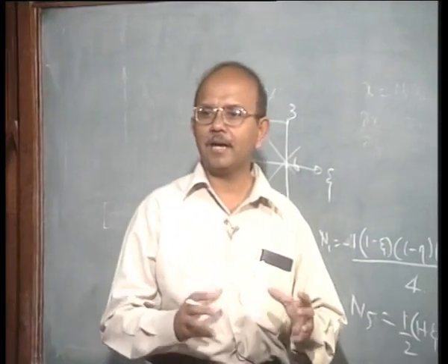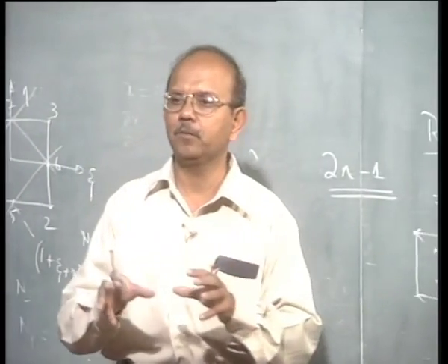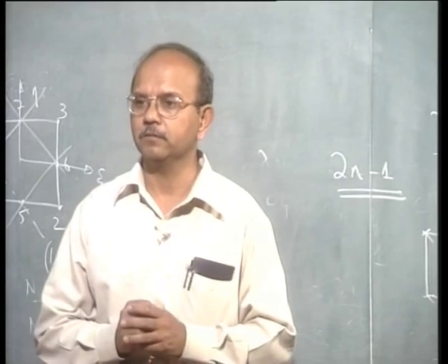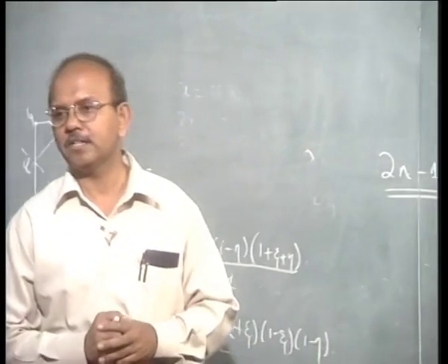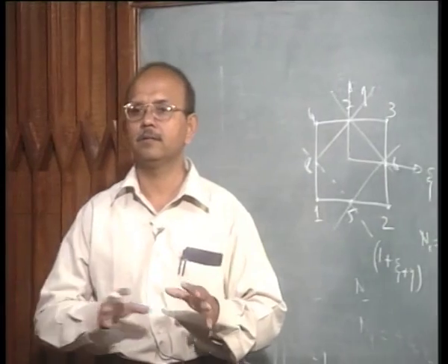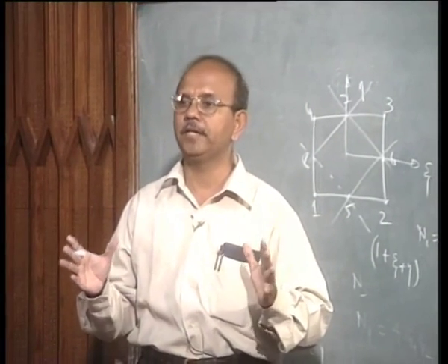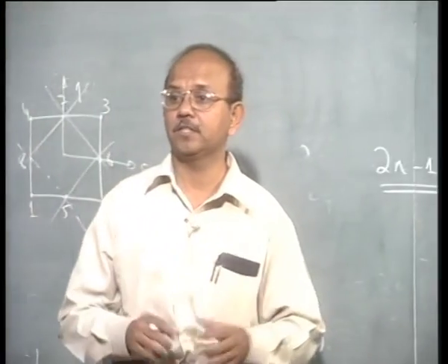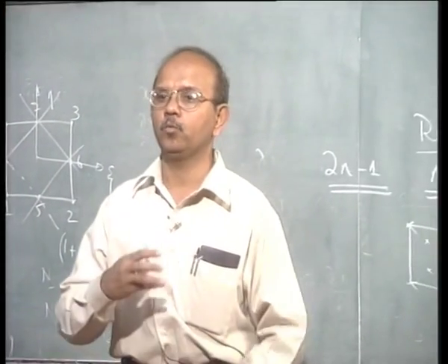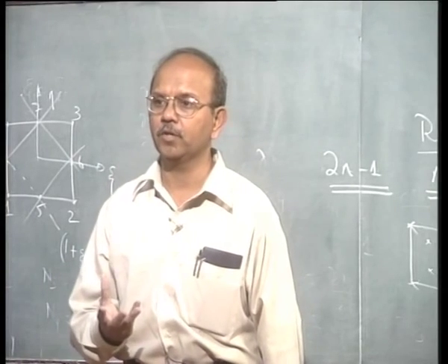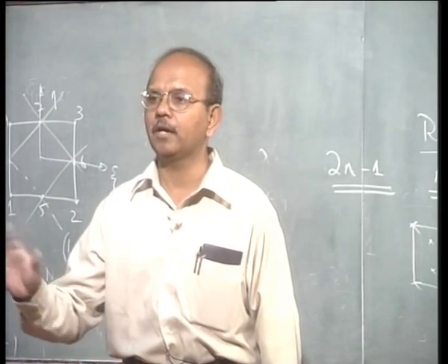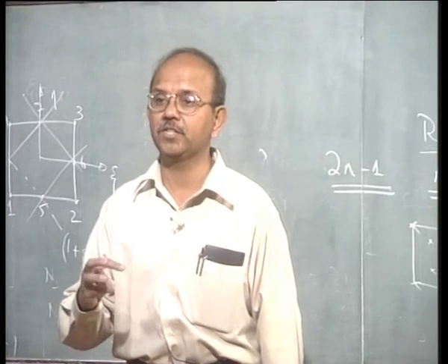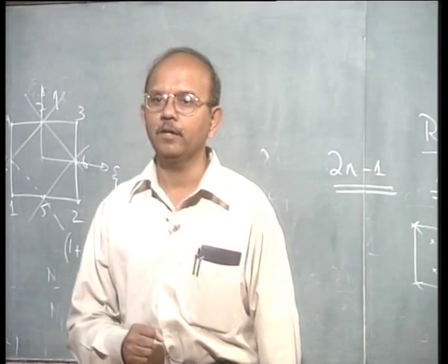Now for that we have to understand finite element, whatever I have done so far, in a proper perspective. After all, in finite element, what is that we did? We broke down an infinite degrees of freedom into a finite set of degrees of freedom. So in that process, what did we do? We stiffened the structure. We said that look, you can't have all your infinite degrees of freedom, you can have only finite degrees of freedom. The structure has stiffened.